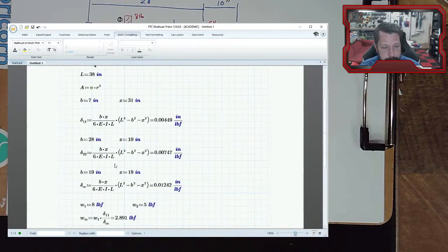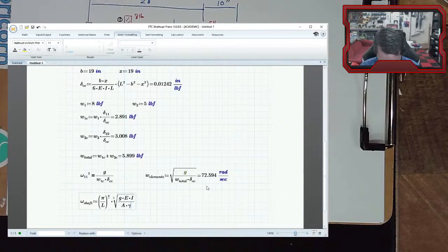We did not. So we have to go look up gamma again from table A5, just like last time. It's going to be a steel. That was a stainless steel, 0.28, that we used. I think I used the same thing, so let's use that again.